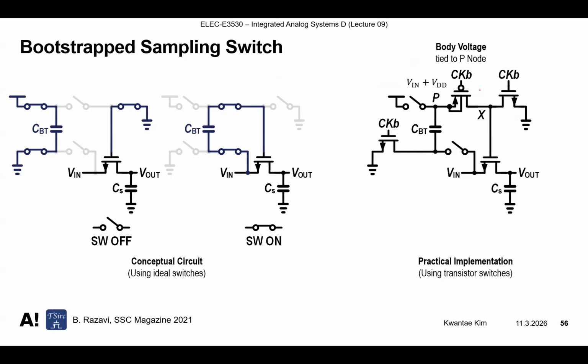And the next thing is much simpler. For this case, we are not controlling high voltages in this region, right? For the bottom plate of the capacitor, only the node here is a high voltage, this node. The remaining part, this part, does not experience high voltages. So we can just keep it as it is. We don't want to worry too much about the MOS transistor safety. So we can just put an MOS transistor there.